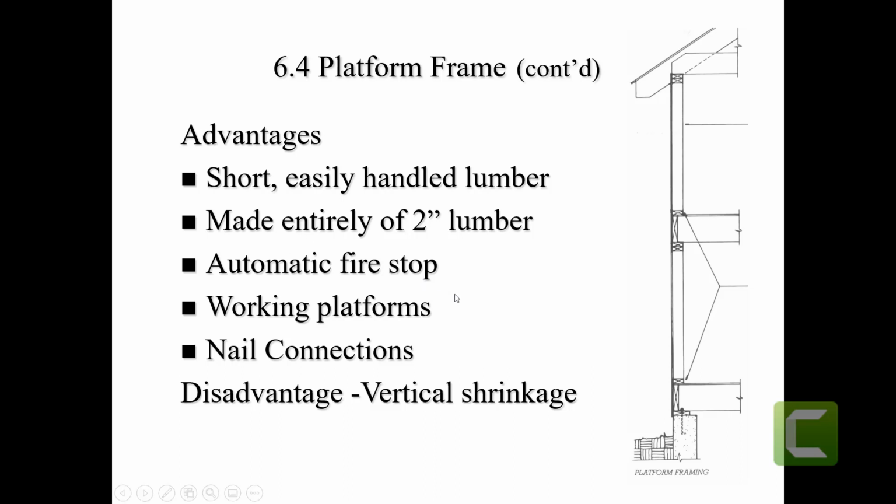Now, the fire stop is what pretty much overtakes all of this, because if you have a fire in the kitchen on the downstairs and it spreads to upstairs, it takes a lot longer. Number two, you don't have to handle such a heavy load of a wall while putting up this wall. You can build it flat, then tilt it back up. And pretty much you're looking at 8 to 9 foot or even as high as 10 feet walls to be put up. A lot less labor intensive, faster to put up. The lumber itself is cheaper. So therefore, we use